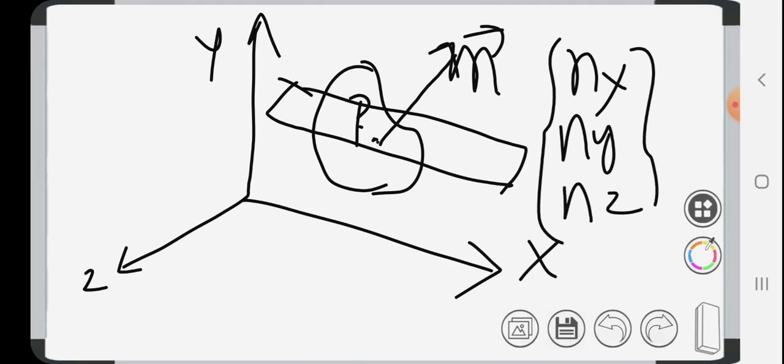So these values you know. The plane is not the x plane, not the y plane, not the z plane. So you cannot use the stress tensor with sigma x, tau xy, tau xz. Such a stress tensor cannot be used in this case. That can be used only in rectangular coordinates, if the plane is x, y, or z. So if you are asked to find the stress at a point on an arbitrary plane with direction cosines nx, ny, nz, what will you do?